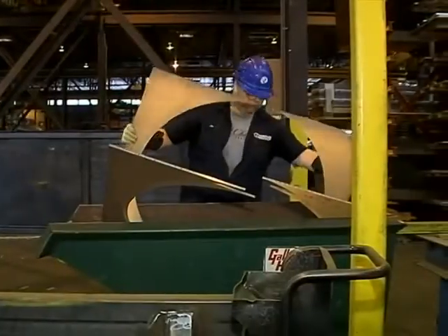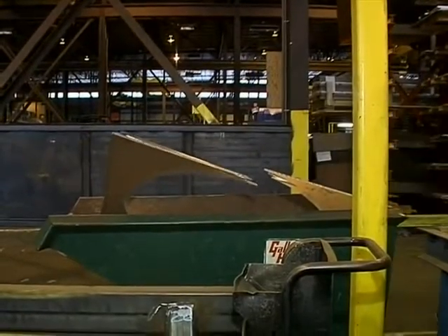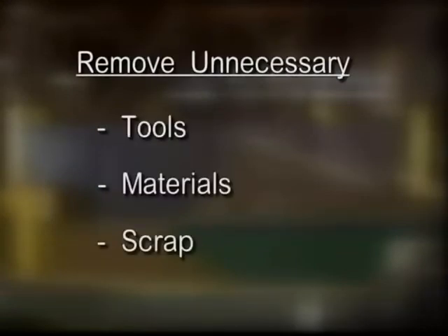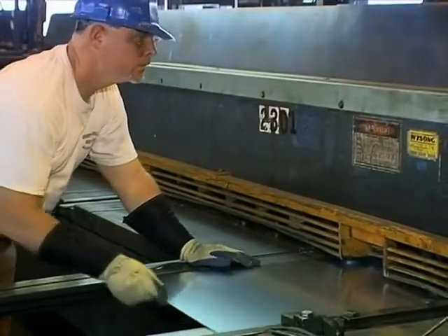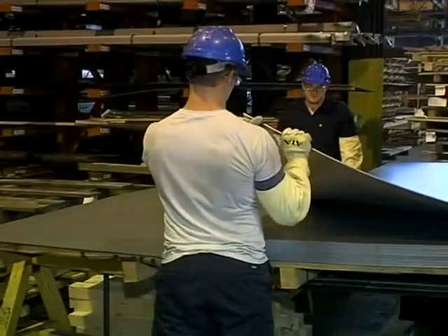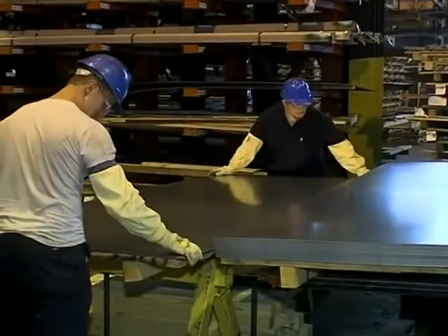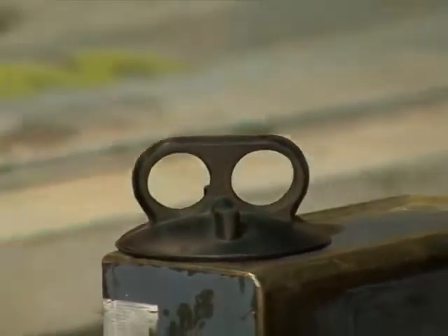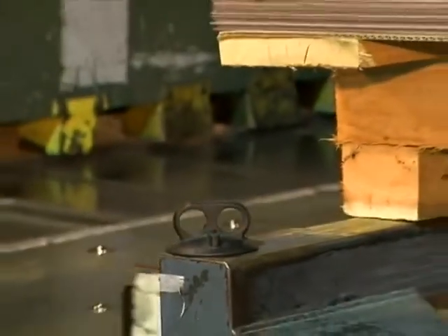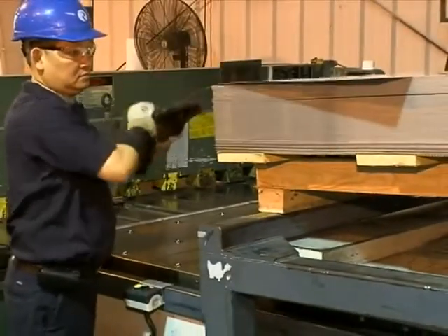Conduct regular inspections of your work area to identify and remove laceration risks. Make sure all unnecessary tools, materials, and scrap have been removed from your work area. While working, keep all guards and controls in place. If the process is not automated, try and use equipment that will decrease the need for you to handle sharp material. For example, if you are working with metal sheets that have razor edges, utilize a tool that will minimize the need for personal contact.